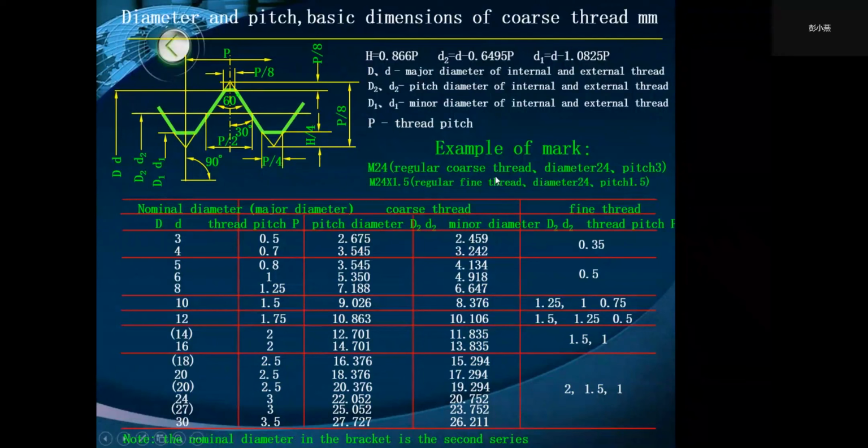The metric threads are designated by M followed by major diameter and a pitch in millimeters.